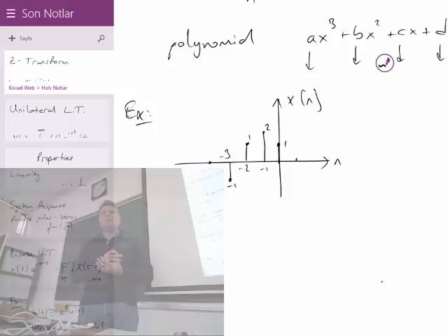Now, can you write me the z-transform? It's nothing but writing the same signal in the form of a polynomial, a z polynomial. This representation could be imagined as a vector representation, a vector from minus 3 to 0 with 4 elements, a vector of size 4. But a polynomial is also an alternative representation to that.